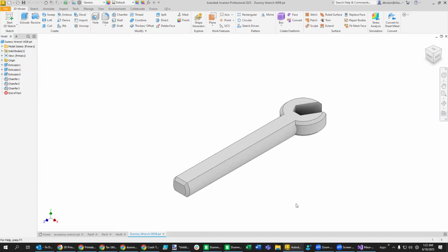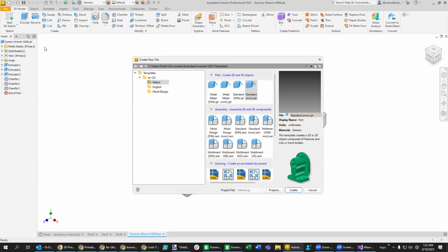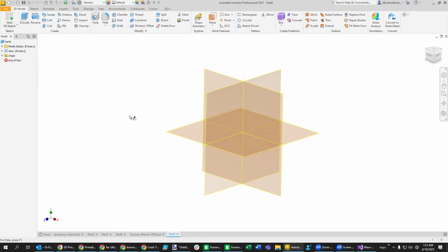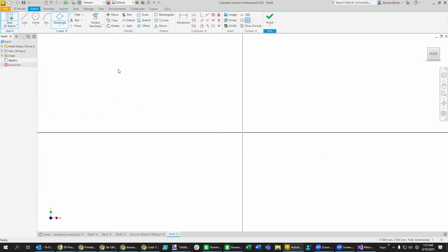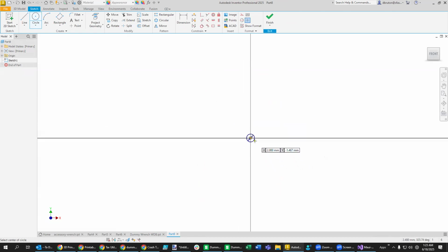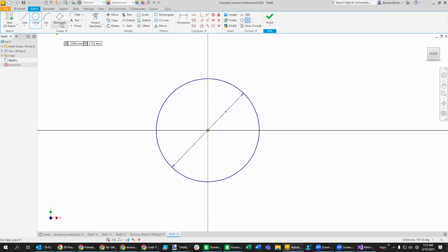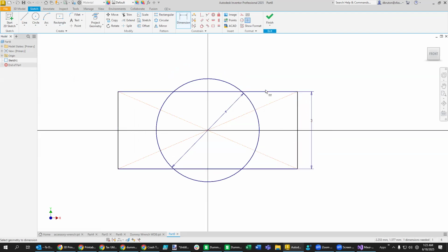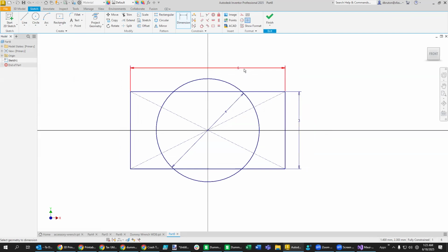Now, let's see how we go through this maybe a little bit faster. Remember, we went up here, we said File, New, Millimeters, and we said Sketch. We selected the XY plane. We made a circle. And here you can actually type in 4 without having to make that dimension. Then you can use the scroll wheel to zoom in. We want that center rectangle, 2-point center rectangle. One dimension is going to be 3, and the other one's going to be 6. So right here, we want that to be 3. And then click and drag up here. We want this to be 6.